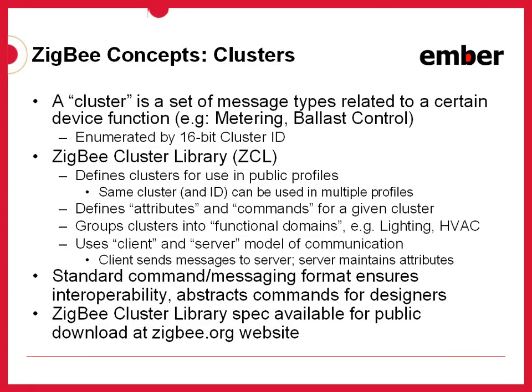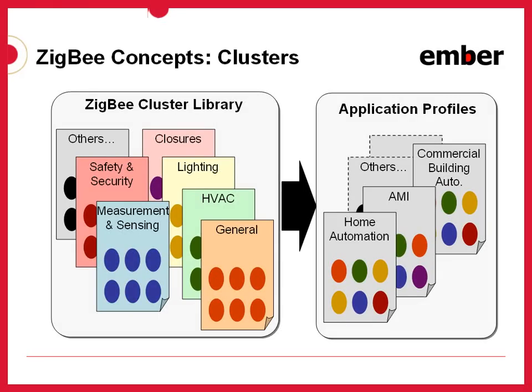So if you're interested in the ZigBee cluster library, I encourage you to go to the zigbee.org website, and you can download the ZigBee cluster library for free. So just to depict this graphically here, we have a set of clusters which are grouped into functional domains. The collection of all clusters in all domains is the ZigBee cluster library, and then you mix and match clusters from different domains into application profiles to suit the needs of devices within that profile.